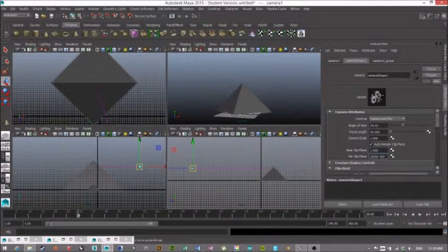And your far clip plane, just throw like 5 or 6 zeros in it when you're dealing with architecture stuff. In Maya, you typically work in a really, really small scale, much smaller than architecture, but if you import your building at actual dimensions, you may dump it in and you'll hit F to frame the geometry and you'll see it for a second and it'll disappear. All that means is you have a clipping plane problem, so just select the camera that you're dealing with, go into the far clip plane, and just increase it up to like 1,000,000 or whatever.